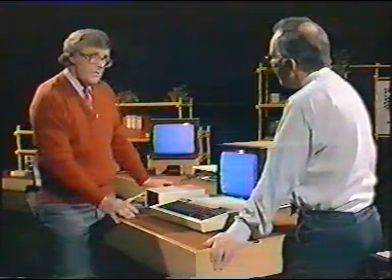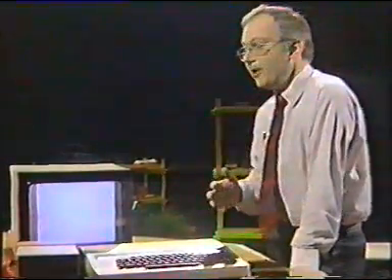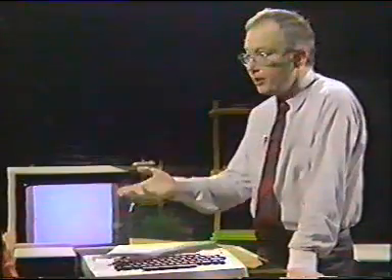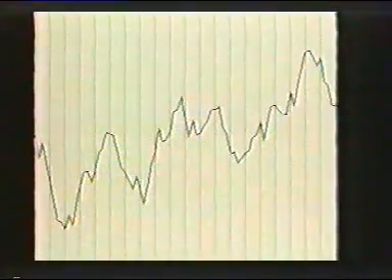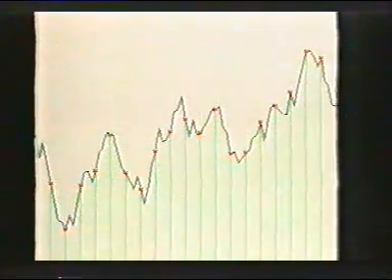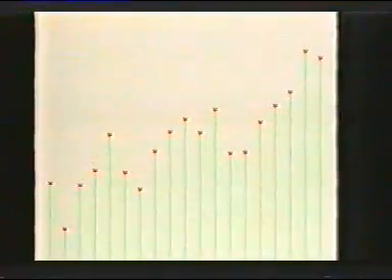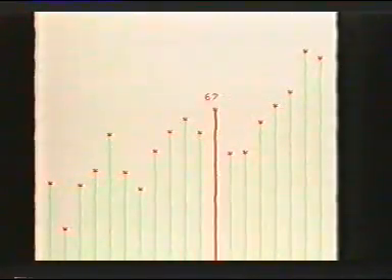How do they actually work inside the machine? Okay, well, I've got a program, needless to say, to illustrate this. The fundamental thing about analog quantities is that they vary. They don't just have ons and offs, they vary. And you can see the graph here, which represents the voltage of some signal against the time. And as you said, the microphone and the pressure pad are both producing voltages. Now, the computer samples those voltages at regular intervals, maybe every 50th of a second. And it then decides what the height of the signal is at those moments in time. And it reads those numbers in to the computer. That's an analog to digital conversion. We fed an analog signal in, and we've got a digital result to deal with.